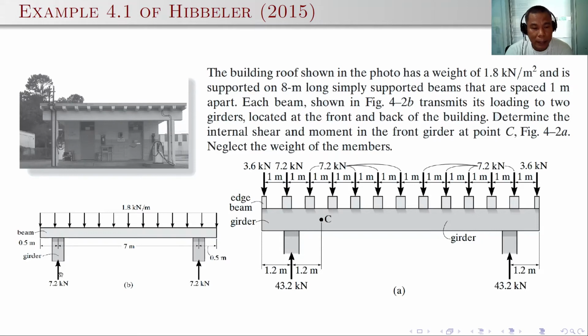Sorry for that, I just calculated the reactions mentally, but you need to apply summation of moments to compute the reactions. But for this particular example, it is quite simple because of the symmetry of the structure and the loading. We can just multiply the loading by the total length and divide by 2 to get the reactions. That's what I did.